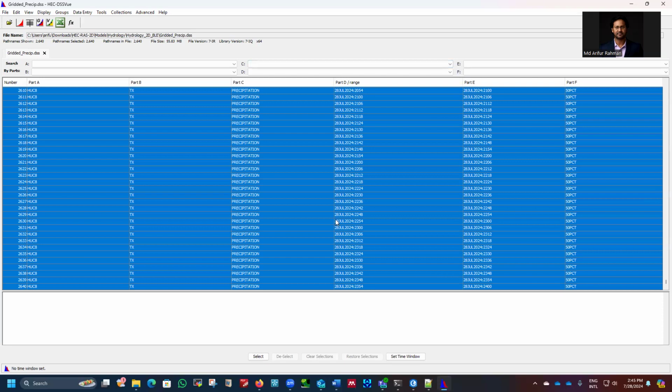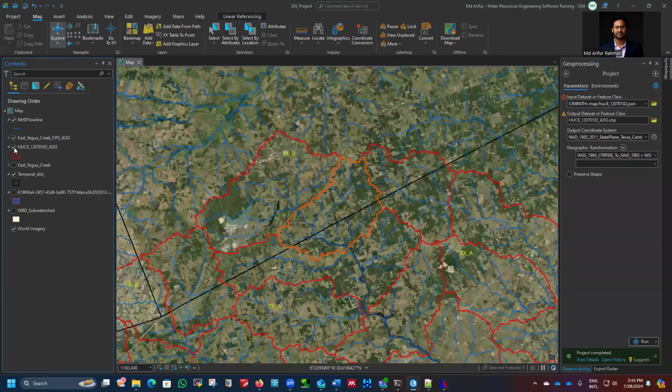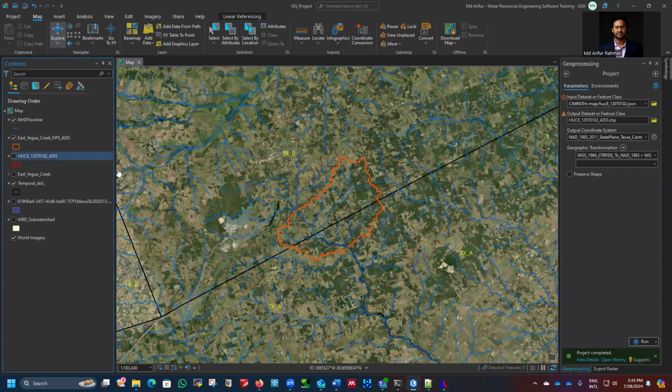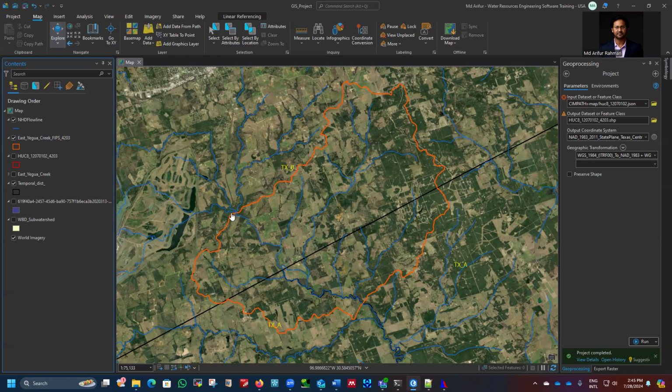So this is basically the main input. And we need to investigate our boundary conditions as well. If we have anything coming from upstream, let me turn this off and see, because that's the stream draining to this study area. So we have to use an inflow boundary condition here, right? We have to know the flow coming from upstream to this boundary. And we don't have any other inflow coming to this study area, but only this one.